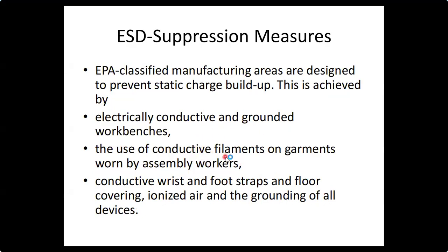They should wear conductive filaments in garments. You should always warn assembly workers who are working in the place. They should wear all the garments, and the workbenches where they work should be electrically conductive and grounded.